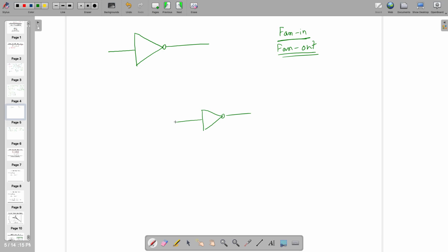We talked about loading effect last lecture. Do you remember the op-amp? We kept it in negative unity gain feedback, and somebody told me that it's a buffer, right? So if the system cannot drive the available load, generally the low resistive load, then you need some buffer, right?